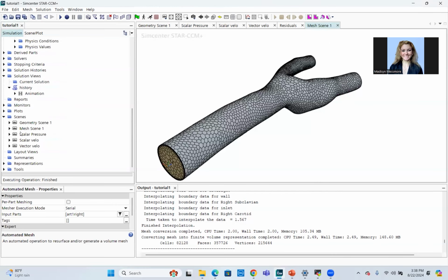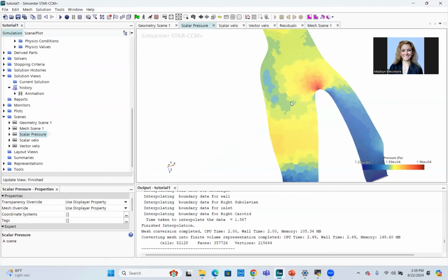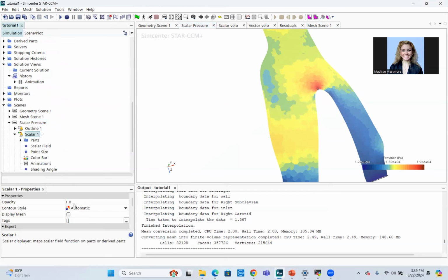That's also another thing: you can usually tell, especially in these scalar plots, like you see how it's got those clear chunks. That is your mesh. Those are the edges of your cells. So if you can clearly see this, like that's way too big, then you'll know I really probably should refine it. Or if you really can't refine it, then you'd be like, hee.